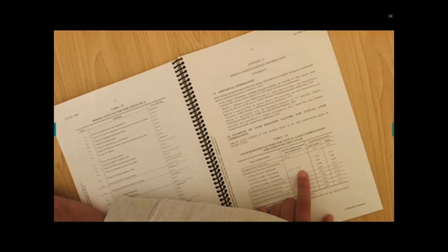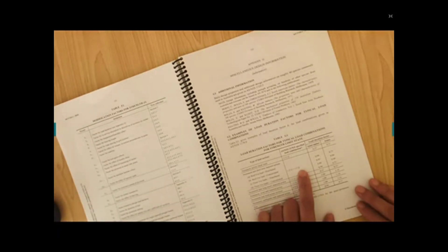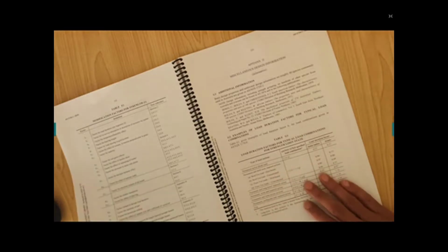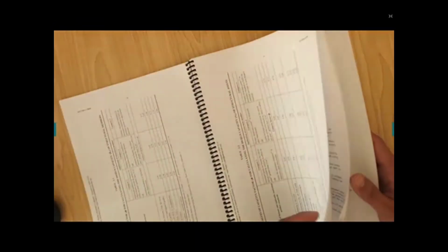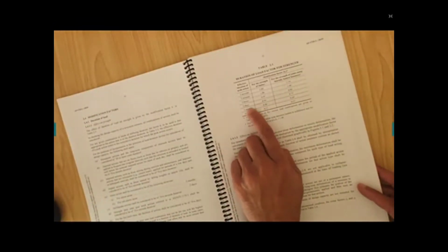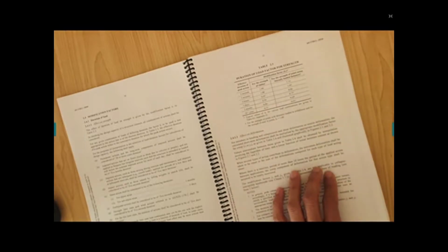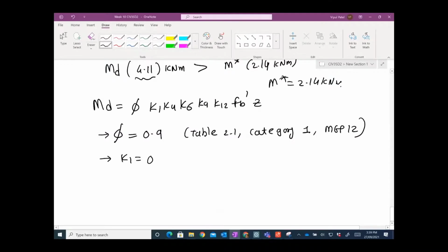In that case, let's say we will have a K1 value of 0.94, roof live load distributed, because we have it on the roof side. So we take 0.94, and by the way, that is for 5 days, as I showed you on the table. So that is coming from here, 5 days, 0.94. Someone might say, no, I don't agree, I want to go for 5 months and solve, but you are making it expensive. So for our case, 5 days, 0.94, office building, 1.2 G plus 1.5 Q. I'm not saying it is the critical one, and for our course we are not checking all of these, but I think you are in a position to take into account all the cases in the real world. For your exams, if you come across this normal situation, office building and all, we typically do it for 5 days, because it's 1.2 G plus 1.5 Q.